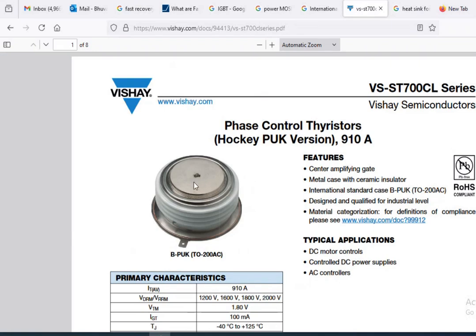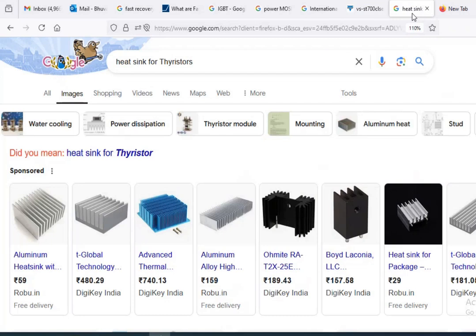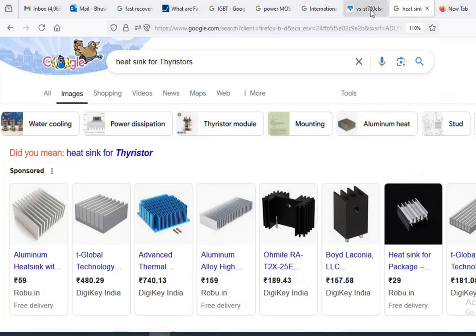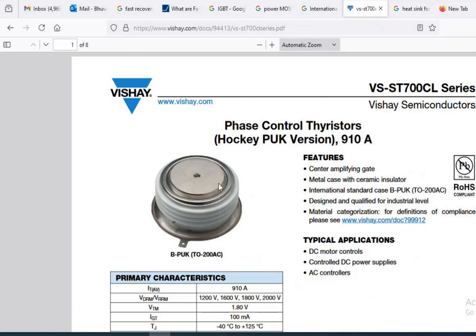And when it is bolted together like this, if we look at the thyristor here, you can see from this particular hole, along with this, it will be bolted. So whatever terminal is available, if it is cathode, it is essentially connected directly to the metal body of the heat sink. So this will also be carrying the same current. It will be actually short circuited with the other terminal of this SCR.